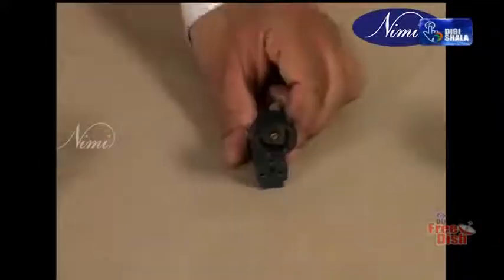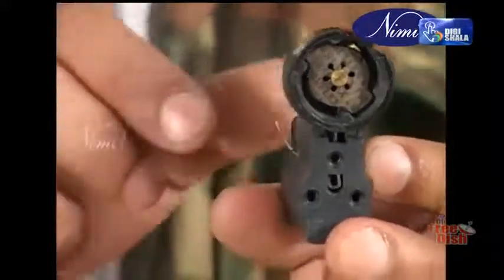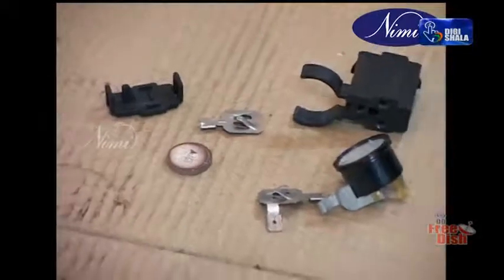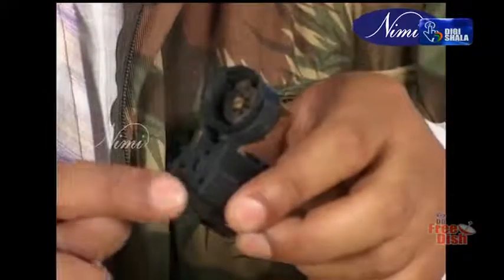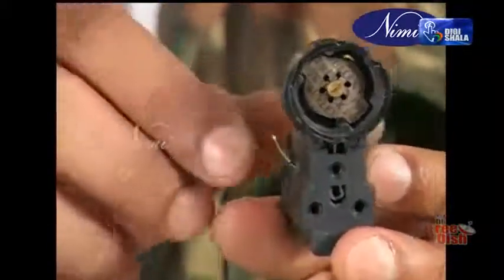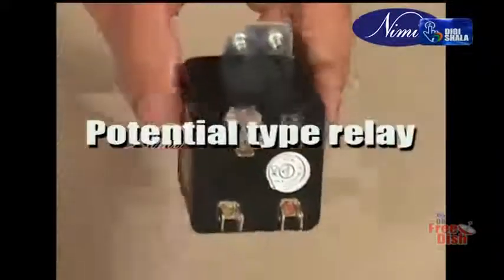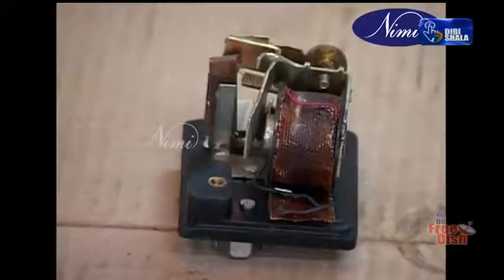Solid state relay. The solid state relay does not actually use a switch to take out the start winding. When the compressor is idle, the relay is cool and its resistance is very low. When the voltage is applied, the start and run windings are energized simultaneously and the compressor starts within a few seconds. The start winding current that is passing through the relay causes the relay to get quite hot. Potential type relay. A potential type starting relay is wired with a capacitor.